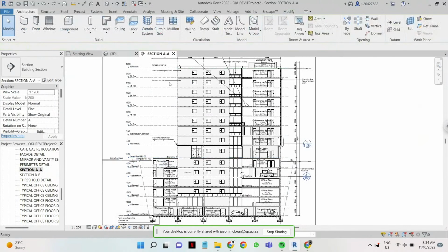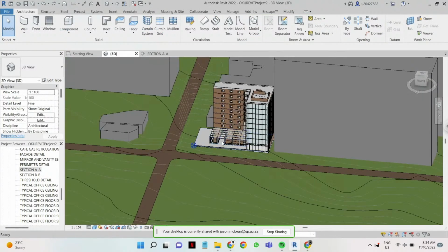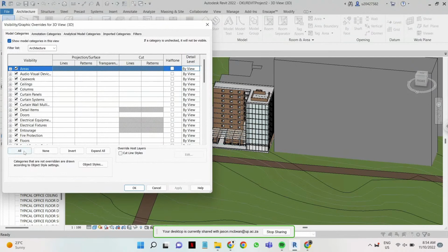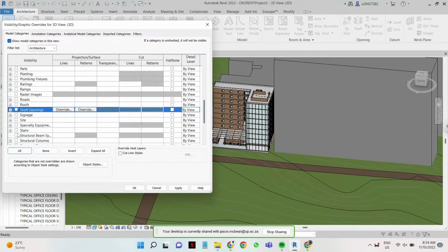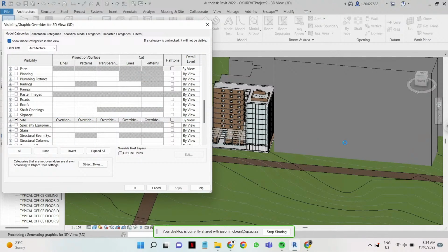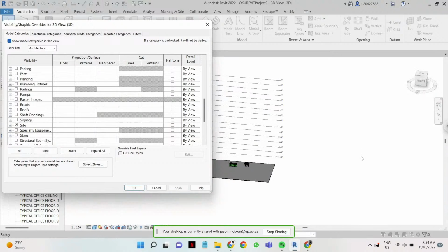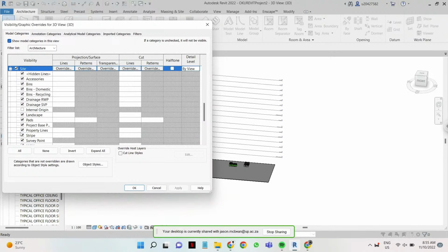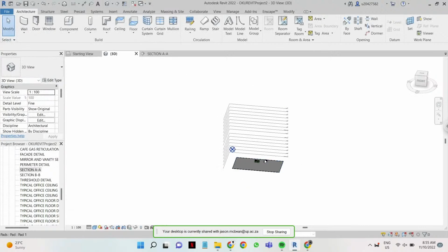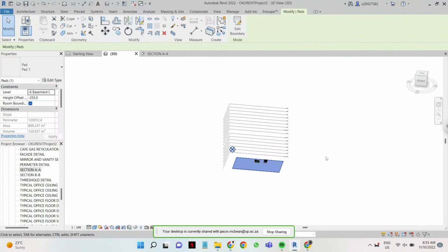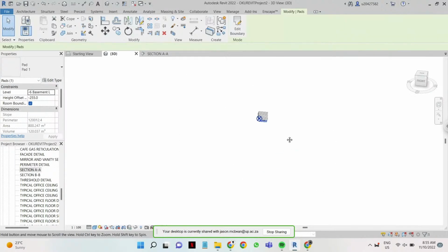So go back to 3D view. Now, in VG, you're going to switch everything off in your views except the site information. This is a quick way to clear the view of everything very quickly. Then we're going to have our survey, and I want my project base point to my survey point. Good. Don't worry, that's a basement, that's probably part of your site; you've probably used a